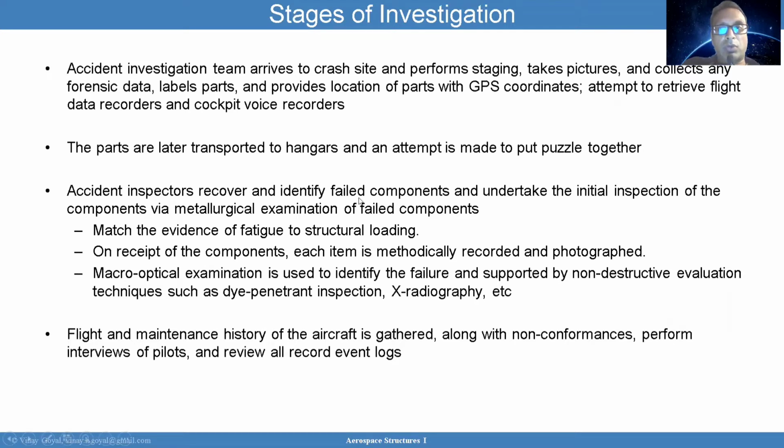Inspectors recover and identify the failed components. What you want to really look at is, very visually, an initial inspection of the components. And you also want to perform a metallurgy examination of the failed components, because if you go through that exercise, you may find failure modes that could point you to the root cause of the failure.